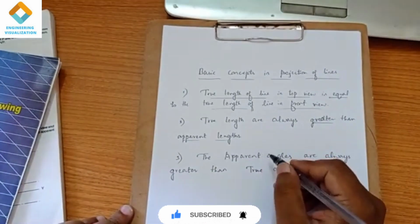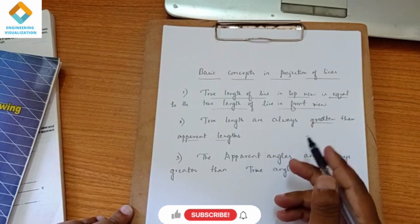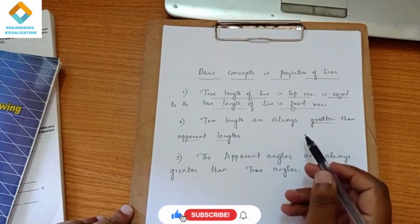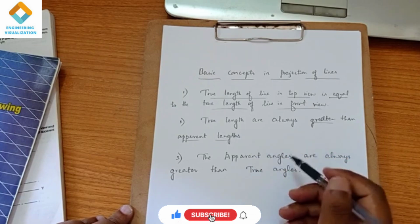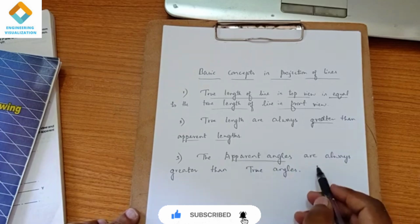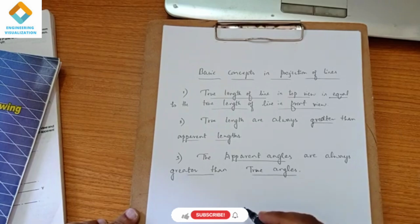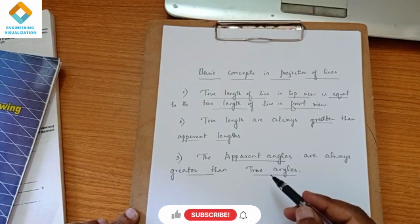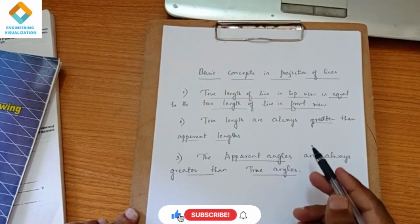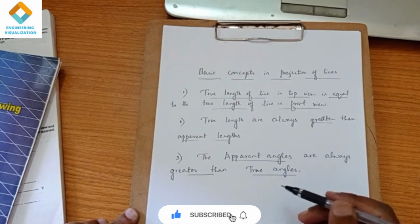And the second concept is that the true length is always greater than the apparent length. Okay, so remember it. True lengths are always greater than the apparent lengths, and apparent angles, which we find out, are always greater than the true angles. Okay, this is one of the differences. So when we are solving the problem, we should make sure the true lengths are always greater than the apparent lengths and apparent angles are always greater than the true angles.